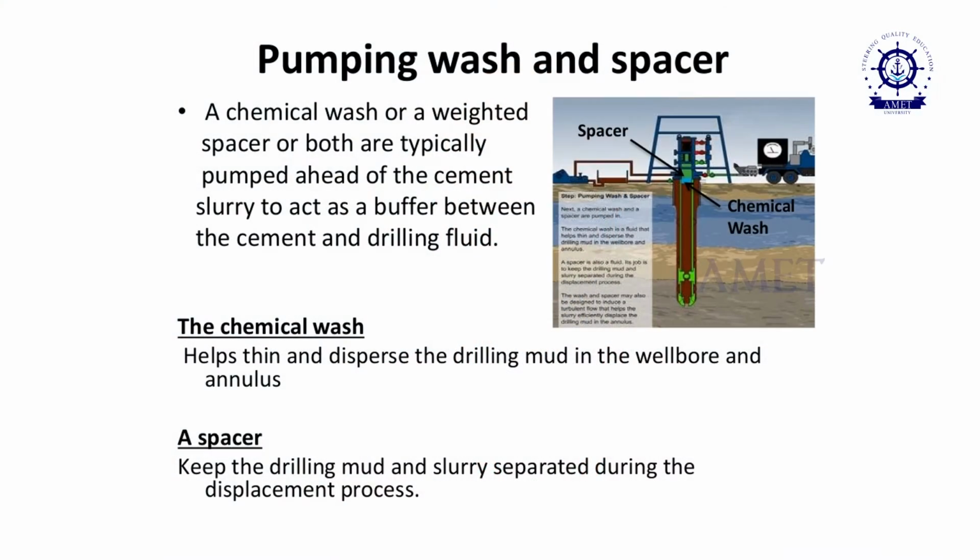First you have to use chemical wash. The chemical wash will help to disperse and thin your drilling fluid. Once it is done, we have to use this spacer. The spacer will make separation between the cement we are going to pump and the drilling fluid we have pumped.